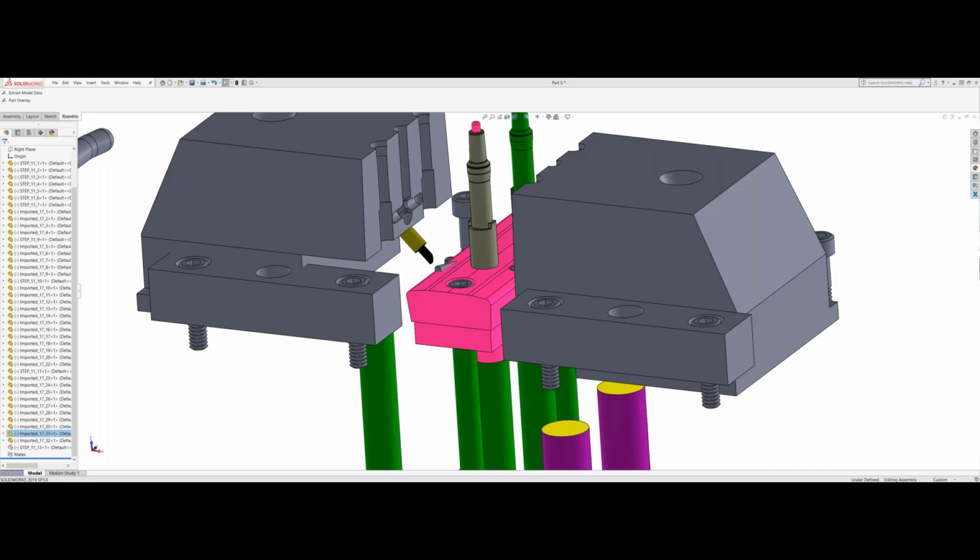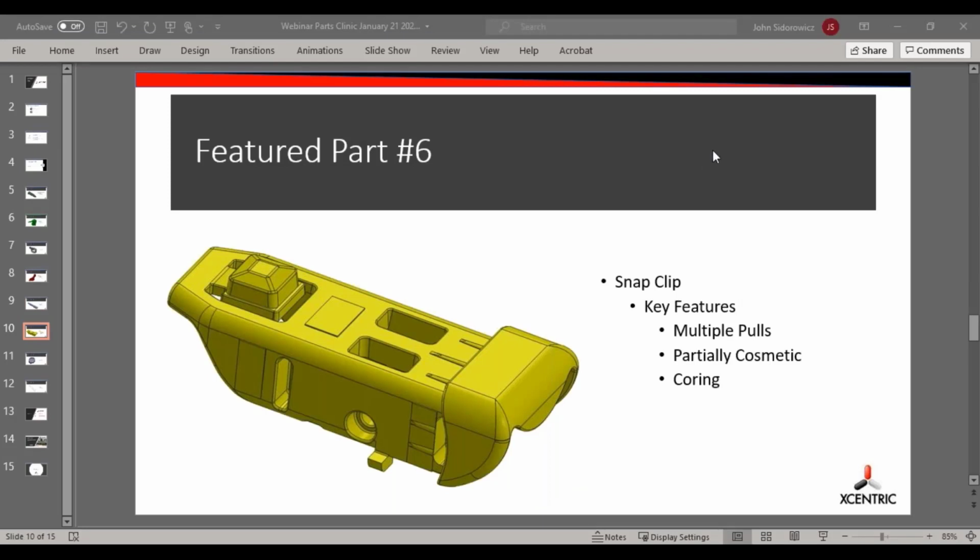If I may just say, the DFM, the mold flows, those are all wonderful simulation tools. Ultimately, though, it does come down to pushing plastic through this tool and actually seeing the results. And then once we do that, we can make adjustments, make recommendations, maybe changes to improve the part, improve the fill, improve the entire process for molding. So another great question along the lines of providing support.